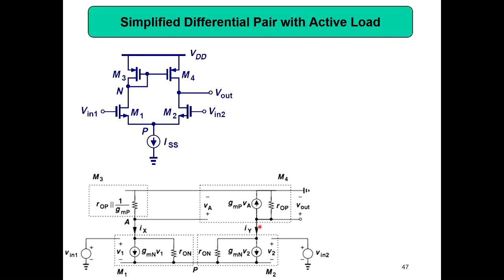And this one I just included to show that this is a very good design. Here you can get the effect of two lines, differential output, in a single line, but the only problem is that finding the differential gain is difficult because it is asymmetric. Then the only way to tackle it is to draw the full small signal and then you can get the gain.